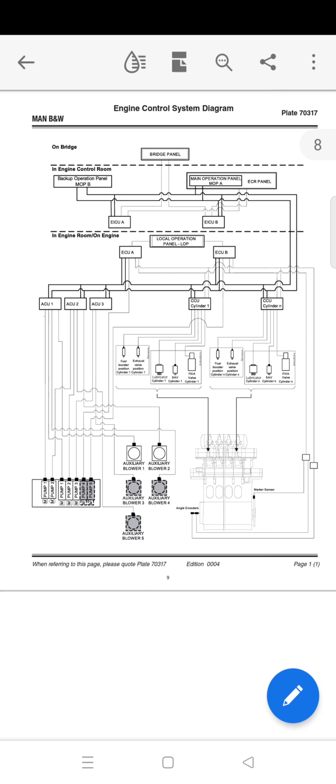The MOP is located in the engine control room. It is a PC with a touch screen as well as a trackball from where the engineer can carry out engine commands, adjust the engine parameters, select the running modes, and observe the status of the control system. A backup of MOP is also placed in the engine control room.